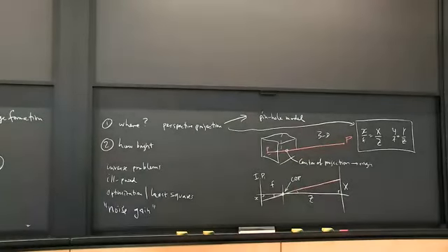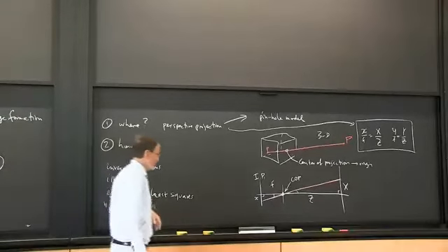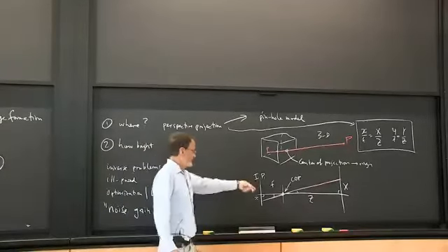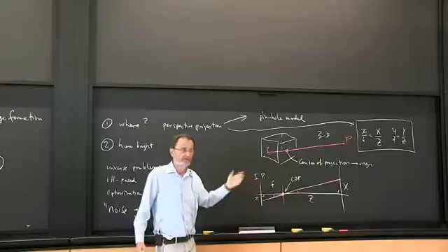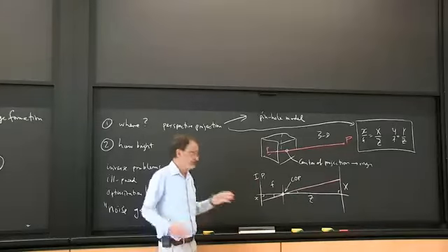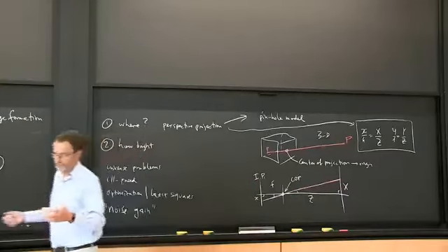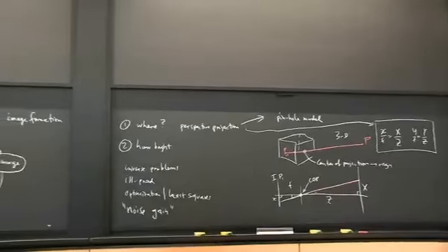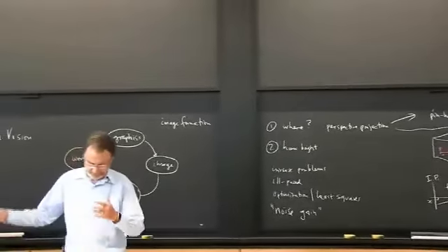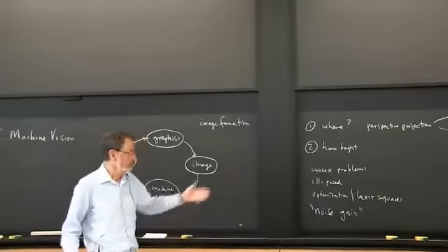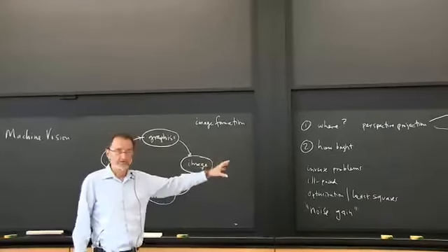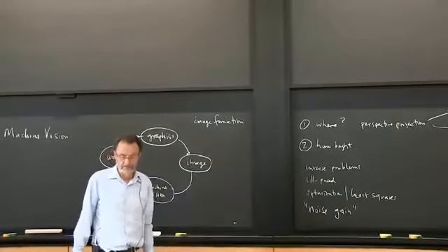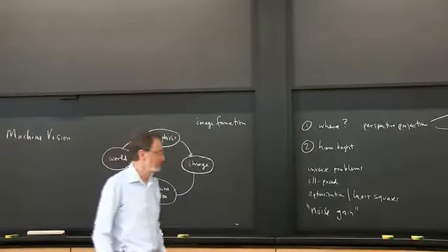So we'll use that as a reference. And so that's going to be our optical axis. It's a perpendicular from the center of projection onto the image plane. And we line up the z-axis with that. That's going to be our z-axis. So it's a very special coordinate system, but it makes the whole thing very easy. And then if we do have a different coordinate system on our robot or whatever, we just need to deal with the transformation between this special camera-centric coordinate system and that coordinate system.